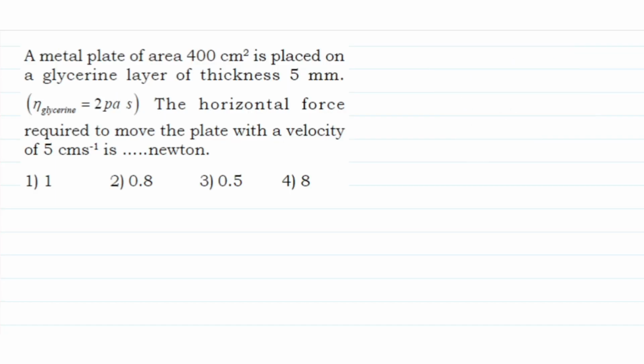Welcome to my class. In this video we are going to be discussing viscous flow related problems, Stokes law and terminal velocity related problems, and Poiseuille's equation when two capillary tubes are connected in series and parallel combination. Those related problems we are going to be discussing.